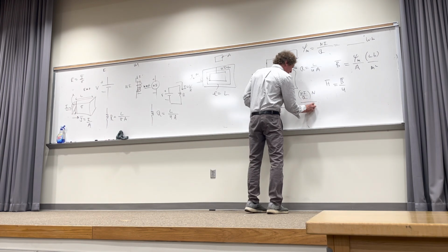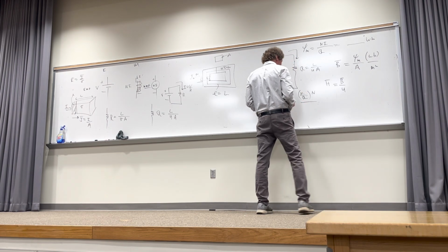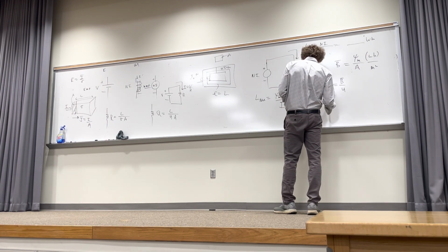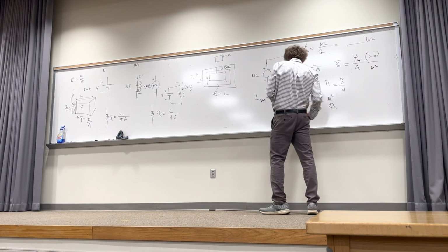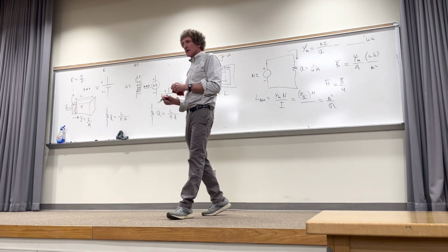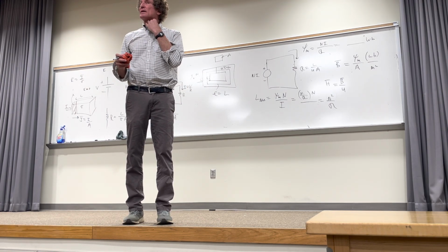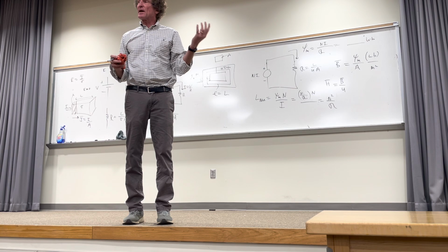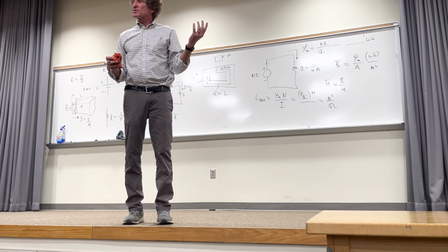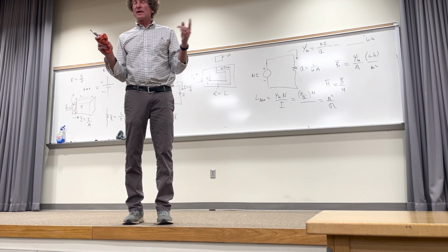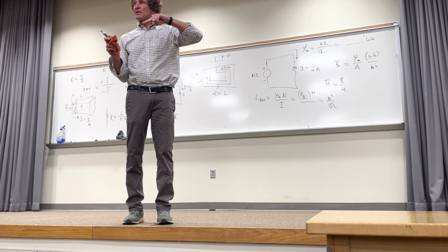So I's are gone. And what you see is what? That's proportional to N squared over the reluctance of the core. You all see that? How many see that right there? All right, that's important, because that gives you a good feel for inductance. N squared is the number of turns on the core, and if I know the reluctance of that core, I got a real good idea what the inductance is, self-inductance.